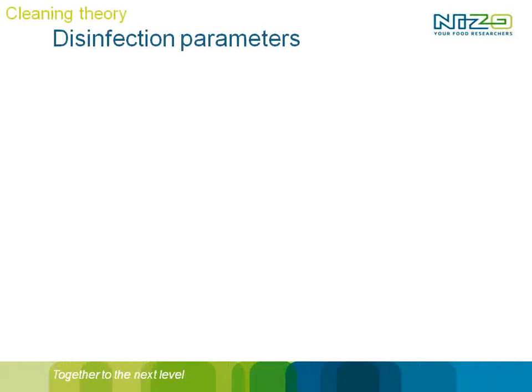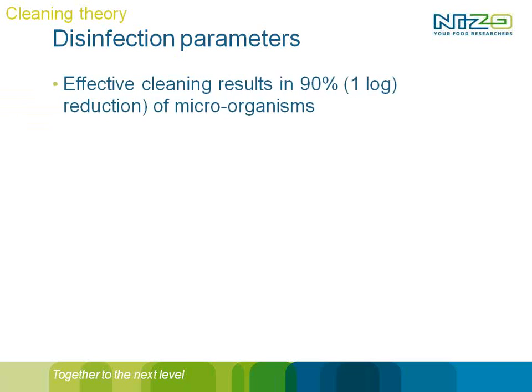Okay, so far the cleaning parameters. Now switching to disinfection. Before we start, disinfection within a good CIP protocol, within standard food production, should not really be necessary, because it's good to keep in mind that a good cleaning process already results in a 90% reduction in microorganisms. And even if you have an 80 degrees C 1% alkaline solution, it even is effective against spores.